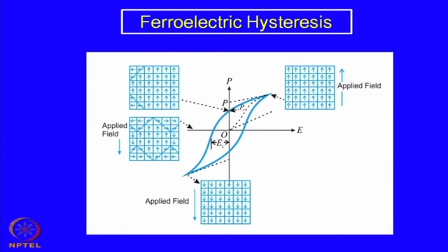Okay. So, as a result of that, there is a phase lag between the applied electric field and the movement of the domains or the change of orientation of the domains. So, we have remnant polarization, and if you want to make it 0, that means to bring the polarization to 0, you have to apply a negative bias or negative field.